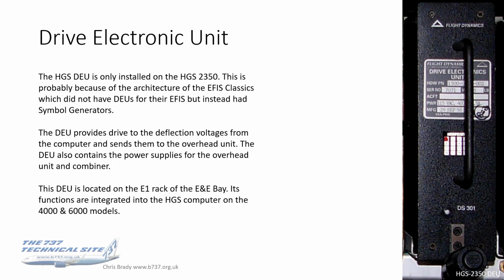On the first of the Collins HUDs, the HGS 2350, they had this extra component in the E&E bay called a drive electronic unit. And I say it's probably because of the architecture of the Classics EFVS setup that they didn't have DEUs for their EFVS, but instead they had symbol generators. So that's why Flight Dynamics would call this a DEU, I guess.